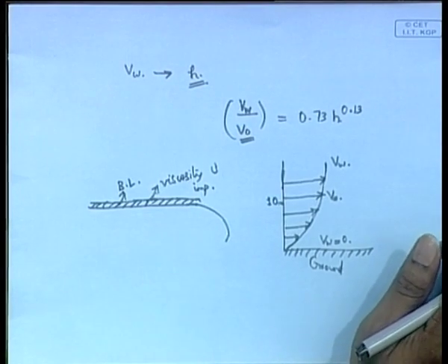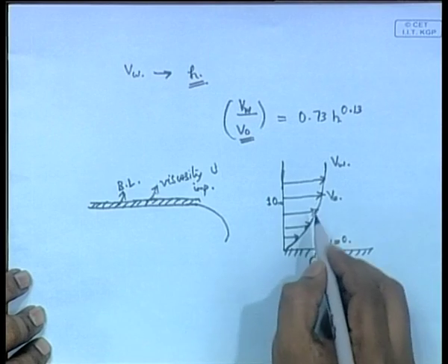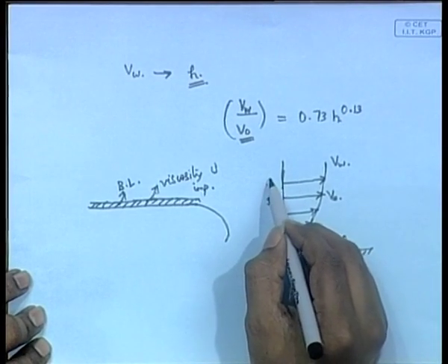The simplest way to define a boundary layer is as the region where viscosity is very important. But a real way of defining a boundary layer is to say that these are regions where the velocity gradients are very large. By velocity gradients, you know it means dou u by dou y, or dou u by dou z. The velocity variation over the boundary layer is very large, and the velocity varies in this fashion, like you see here.